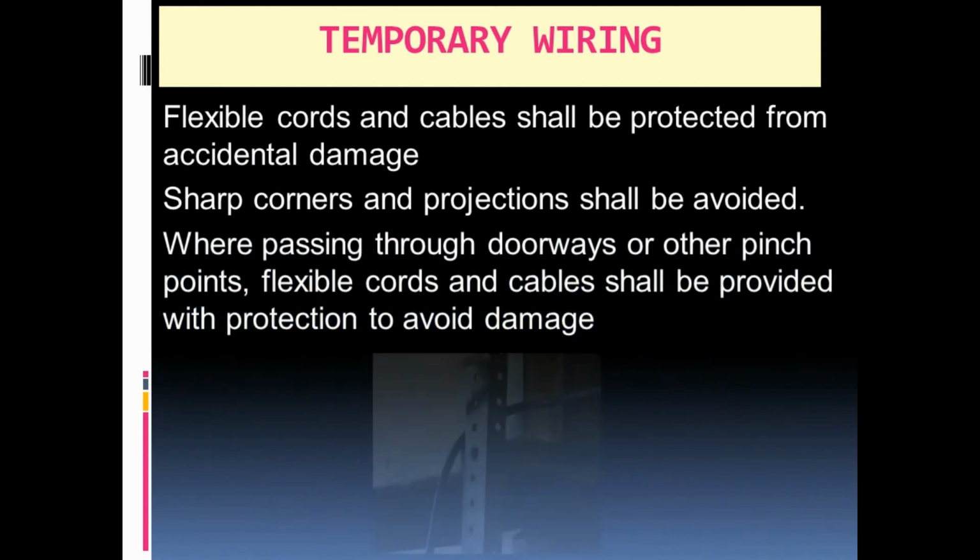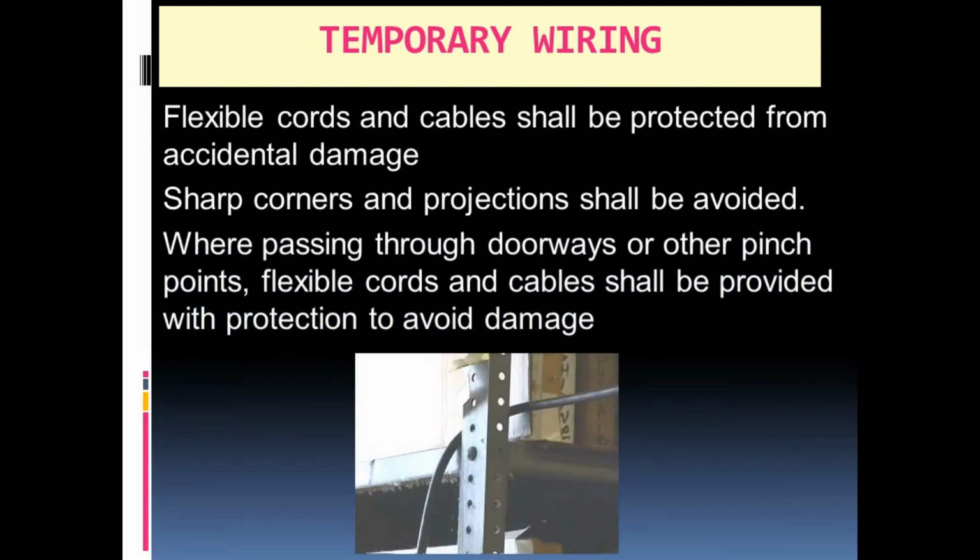Flexible cords and cables shall be protected from accidental damage. Sharp corners and projections shall be avoided where passing through doorways or other pinch points.